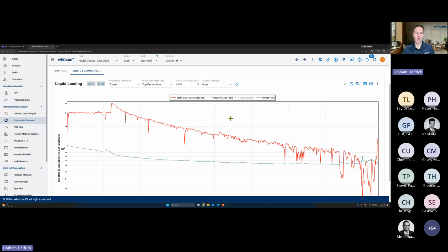So in this particular well, we don't actually have tubing in the well. They're only flowing up the casing. But I agree with what you're saying. If the well had tubing, then we would be showing the minimum rate at the end of tubing. That's what's shown when there's tubing installed. But if you also want to report the liquid loading rate down in the casing, typically at the top perforations, you can change to report at that depth. But at the moment, you have to pick one at a time. So we can't show both, but I think that would be a good idea.